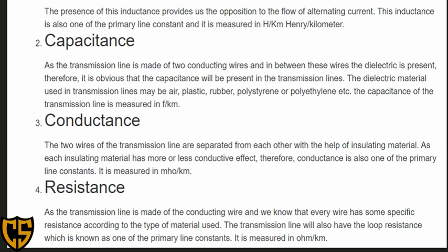So that is one of the units that can be used for capacitance. If we look at a two-wire line, it can act as a capacitor. So we can say that it behaves with the property of capacitance. The change in its capacitive reactance is not noticeable as the frequency applied to it is changed. Capacitance also exists between the wires of our transmission line.